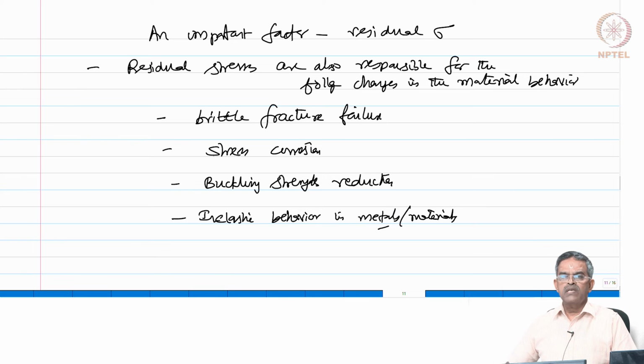The most advantageous factor of steel, as we all know, is ductility, which is a sign to use the reserve strength more conveniently and confidently. So, the ductility of the material enables a thorough redistribution of moments from higher stress region to the next higher stress region.